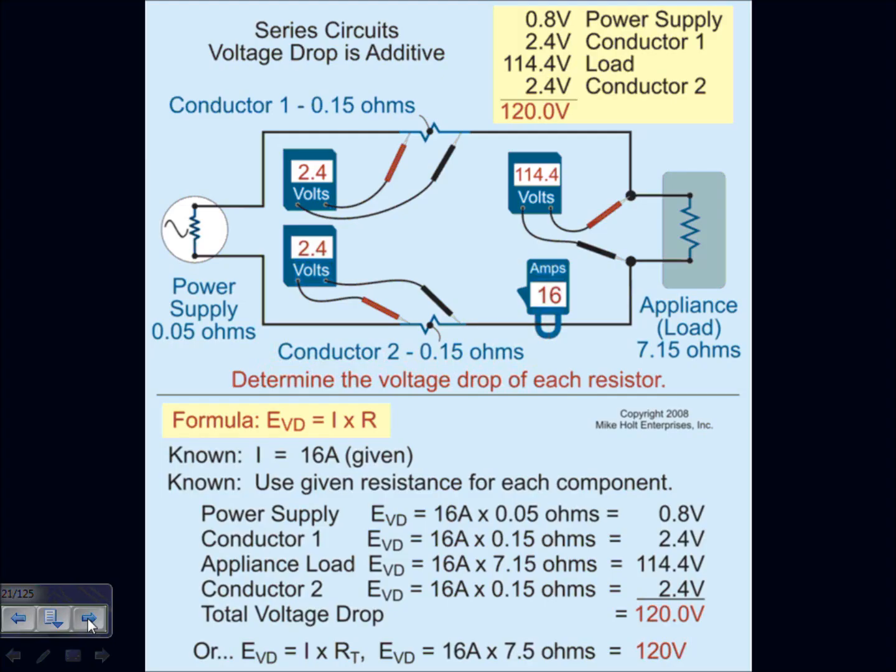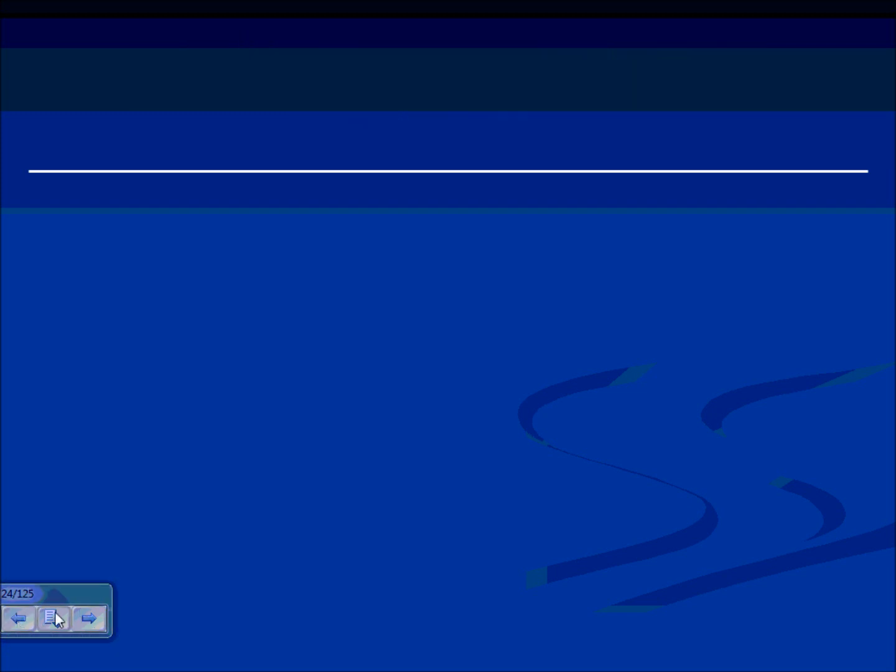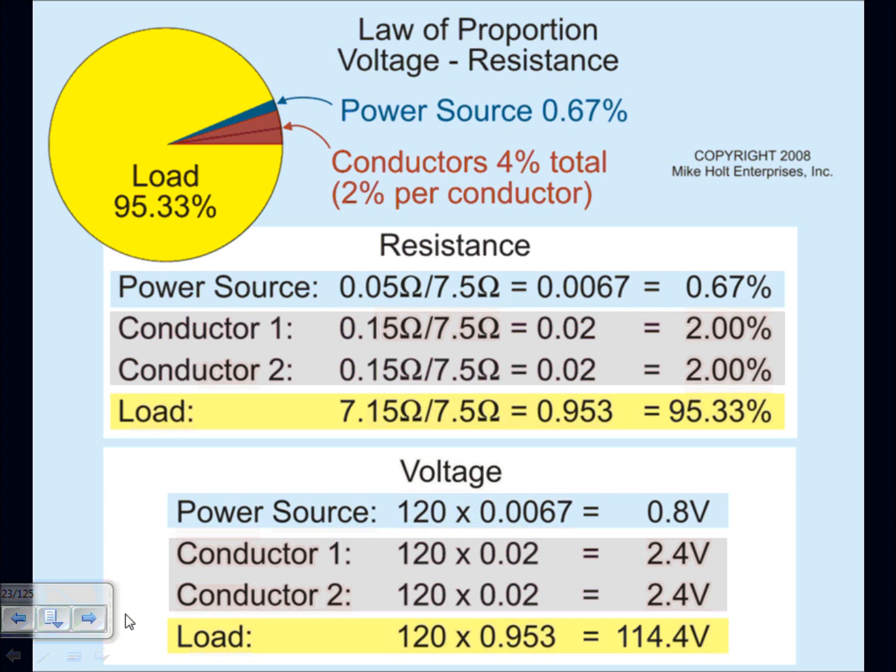I hope you did the voltage drop across each resistor. If I ask you what's the voltage drop across each resistor, you take the current that passes through every resistor and multiply by the resistor itself. You get from Ohm's law the voltage across each resistor, right? Then you add all the voltages. It should equal the power source. Otherwise, you have just created a new science.